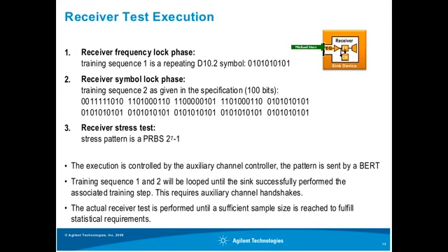And therefore, there are sequences of 5 bits, 5 times the same bit in a row embedded in here and here, which let the sync device synchronize on those bits, and then it finds the beginning of a pattern. And after that, the receiver stress test is actually performed, which is sending a PRBS7 pattern. To be more precise, it's a PRBS7-1.